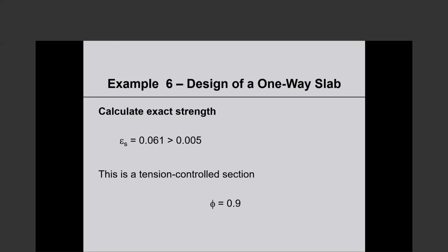Read this one more time, please. If required compression steel in a beam is found high, and if a, that small a, is less than slab thickness, can we distribute rebars in part of the adjacent slab to avoid congestion? Yes, absolutely.